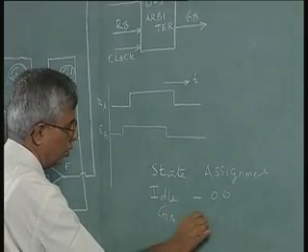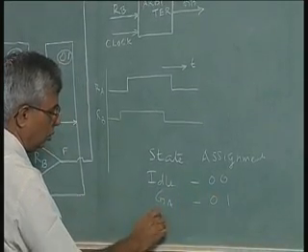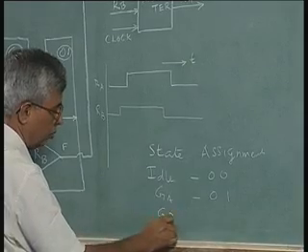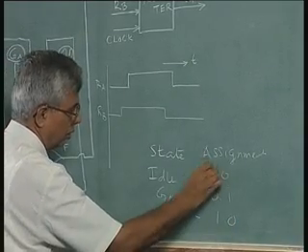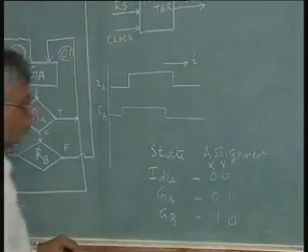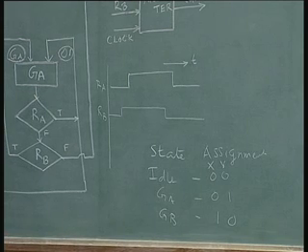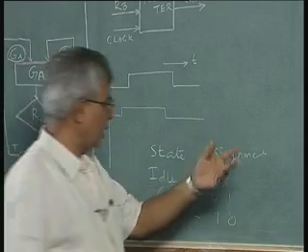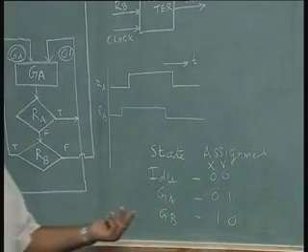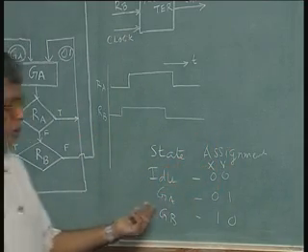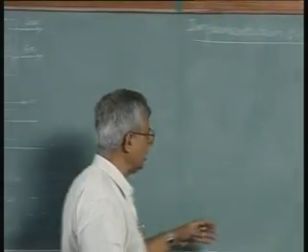GA state, GB state, x and y being the state variables. So, similar to state graph, you draw an ASM table. The first step in implementing an ASM chart is to assign the state variables, the state assignment. Once you do that, you go for the ASM table.